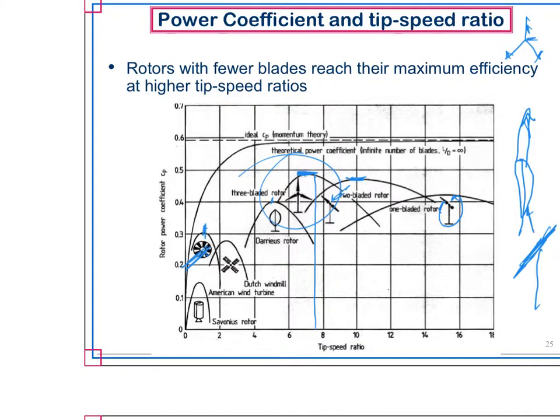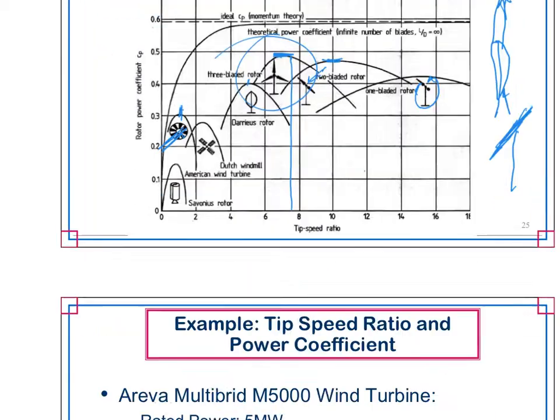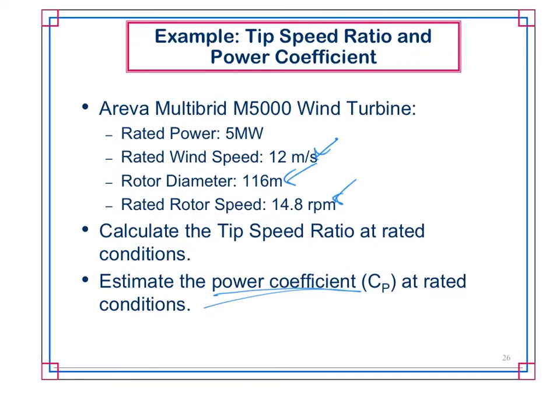So most 3-blade turbines are going to be right in that 7-ish, 7.5-ish range, because that's where maximum efficiency is going to be operated at. And again, you're trying to design systems to get maximum efficiency, so you can see why the maximum theoretical efficiency is most likely where you're going to calculate the best case efficiency.